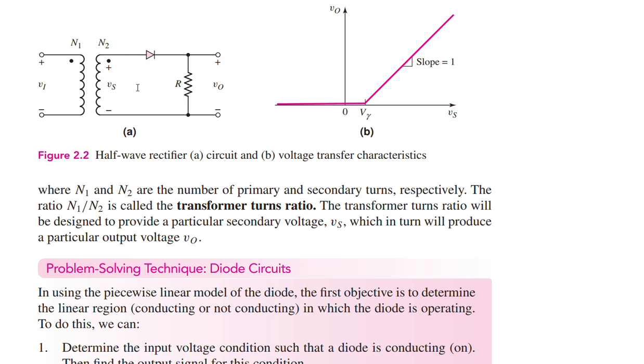But when we are talking about the reverse voltage or the inverse voltage, we are actually looking at the voltage difference between the cathode node and the anode node. It is the voltage at this node minus the voltage at this node, which is the reverse potential across the diode. If we carefully look, the cycle at which the diode will be reverse biased is the negative half cycle, and during the negative half cycle the diode is off, so there is no current through the diode, and the only path for the current to flow is through the resistor. So if the current through the diode is 0, the voltage across the resistor will be 0 because of Ohm's law.